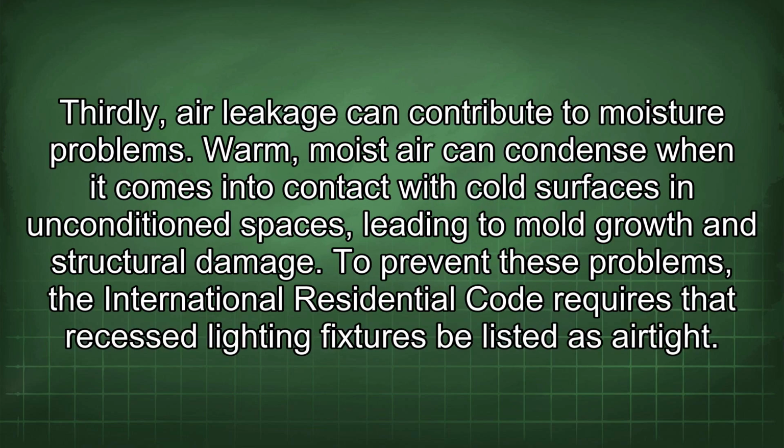Thirdly, air leakage can contribute to moisture problems. Warm, moist air can condense when it comes into contact with cold surfaces in unconditioned spaces, leading to mold growth and structural damage. To prevent these problems, the International Residential Code requires that recessed lighting fixtures be listed as airtight.